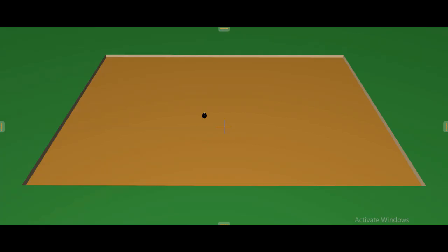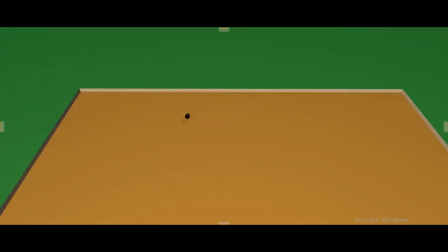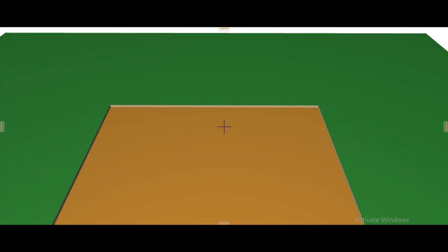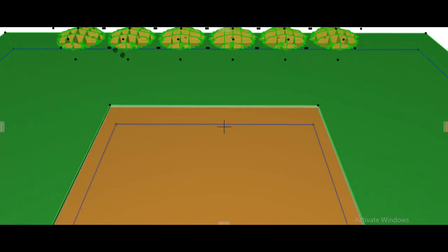But if I want to know the volume of the soil that I'm going to excavate, I go further and multiply that by 150, that is from this upper edge of the topsoil to this lower edge. So this is 150 millimeters I'm talking about. Since it is less than 300 millimeters, I write it in the description column. So I multiply the area that I've gotten times this depth to know the volume of the soil that I'm going to excavate. And further, I dispose of that here. If I do the disposal, I end up with these heaps.